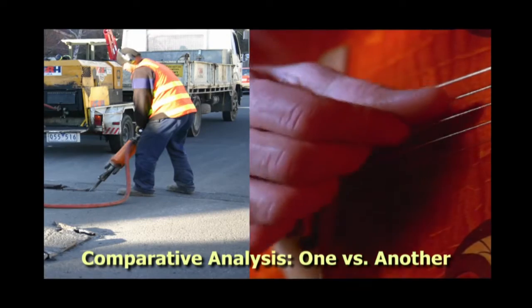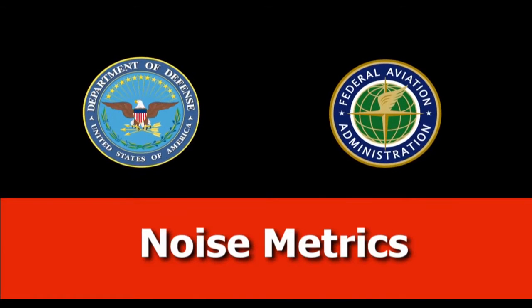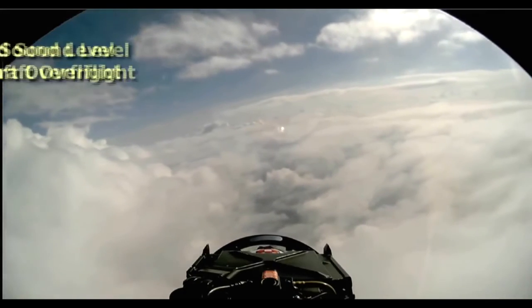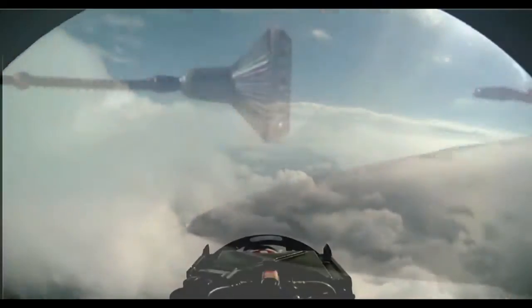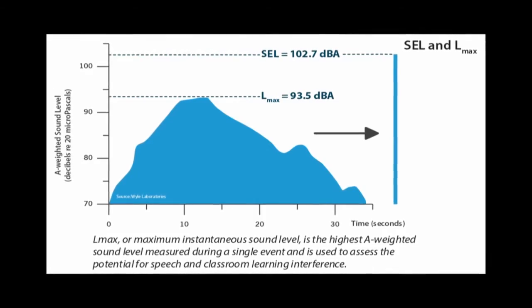The term noise metric refers to the unit that quantitatively measures the effect of noise on the environment. Noise metrics quantify sounds so they can be compared with each other and their effects in a standardized way. The DoD and the Federal Aviation Administration use three common noise metrics to quantify sound. First, a measure of the highest A-weighted sound level occurring during an individual aircraft overflight. This is referred to as the maximum sound level, or LMAX.